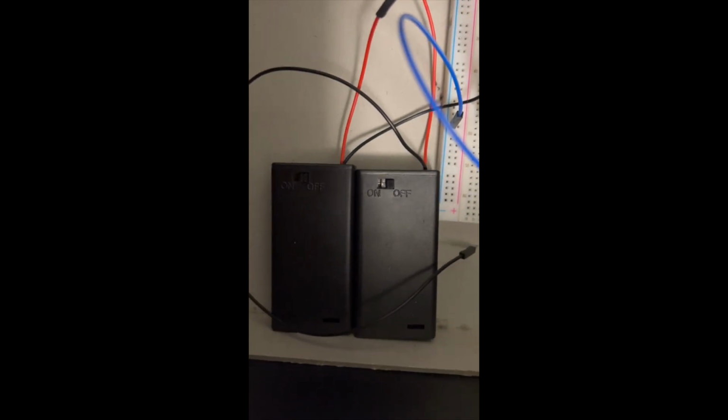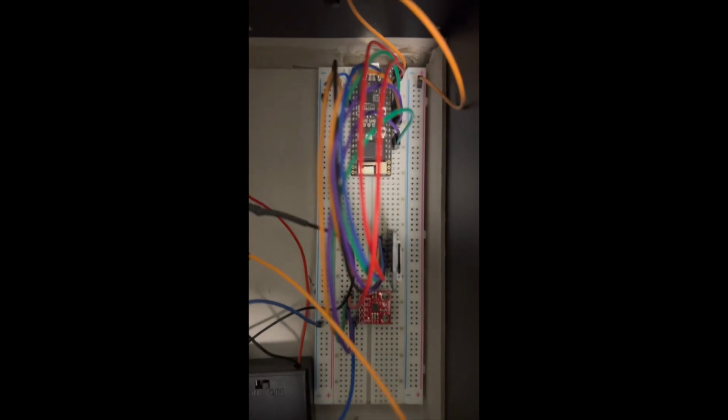The interesting thing to point out here is that the INT1 there, which you can see is on the orange wire, is the interrupt pin. I believe it's GPIO 35, and so that pin will allow us to actually wake up the board from sleep. The only other piece here in the box is our little battery pack so that I was able to get this to run while not being connected. So yeah, there's your wiring overview.